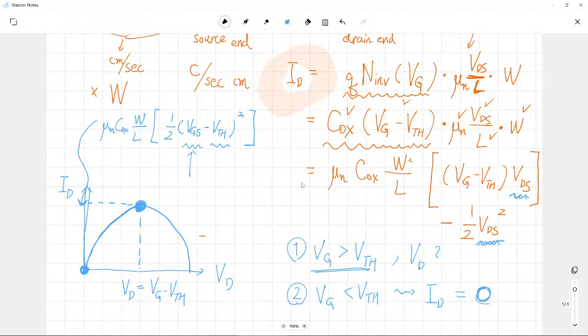But anyway, this is the graph of this expression, and please criticize it. Obviously, this is wrong. The IV characteristics of your device should not behave like this. If this were the case in reality, what happens? You wanted to apply even higher voltage to get higher current, but beyond a certain range, unfortunately, your current is reducing. That cannot be understood, and that does not occur.